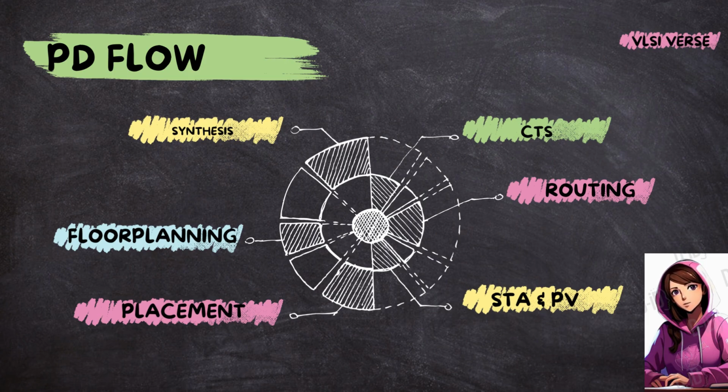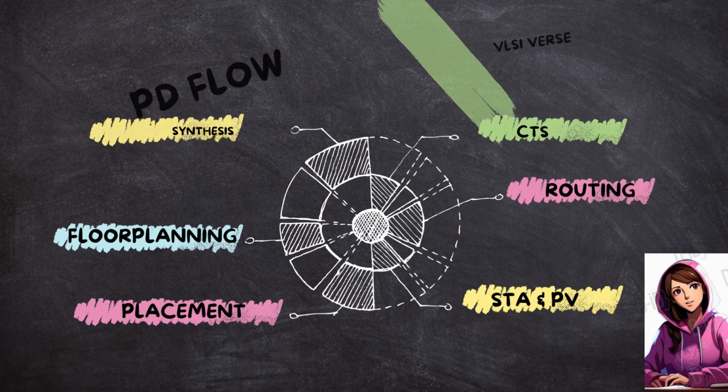First is synthesis, followed by floor planning, then placement, after which we go for clock tree synthesis, CTS, that is routing the clock nets with min skew and insertion delay. Next up is routing, which involves routing the signal nets. Once all this is done, we do the design rule check, DRC, and layout versus schematic, LVS, and more importantly, timing closure, aka static timing analysis, STA, and then we do physical verification, PV, after which the design or the GDS2 file is ready for fabrication.